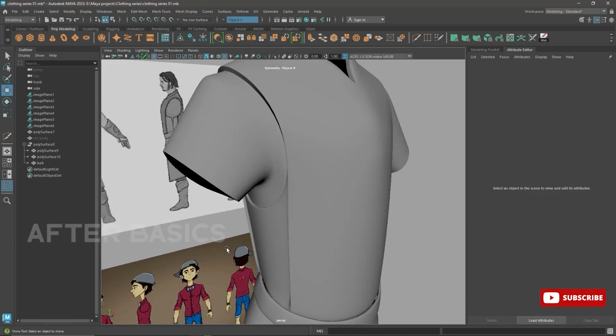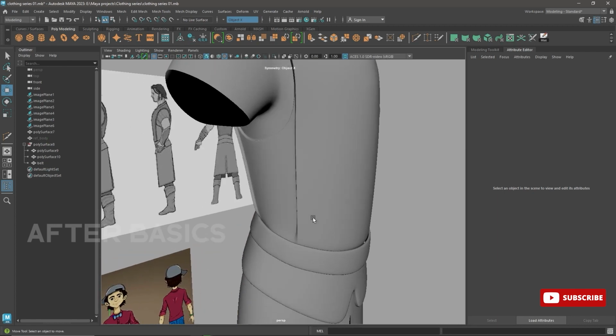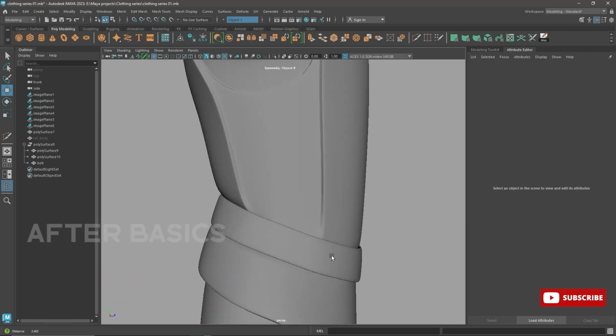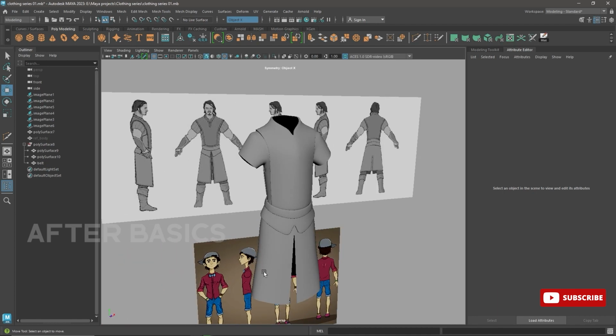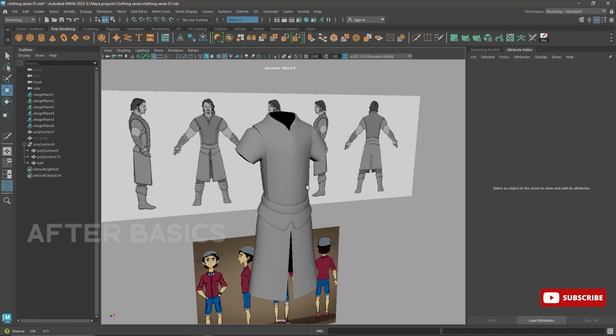Okay, modeling time, just make it low poly as possible, texture it, make it perfect as possible. Then, you can just make a copy of that low poly, add a lot of cuts, a lot of things, a lot of textures, anything like sculpting. You can also put it in ZBrush and add any kind of roughness, cuts, cracks, everything, then bake it over the low poly and you will get very interesting results and it will be wonderful.